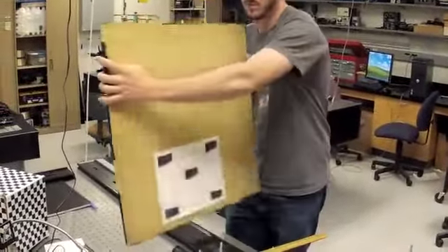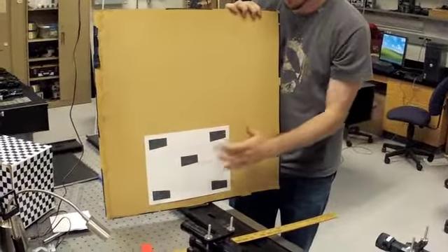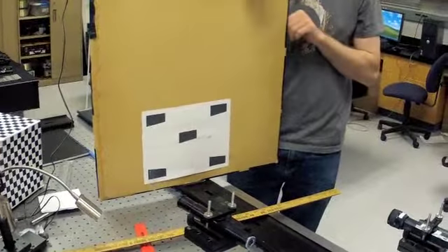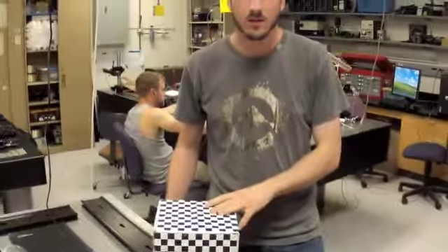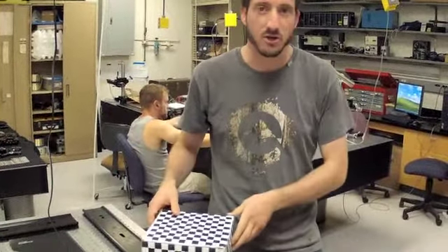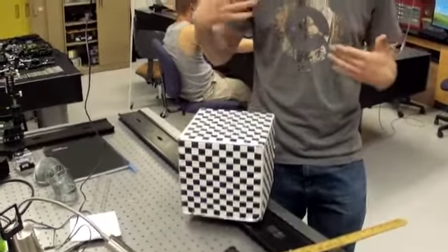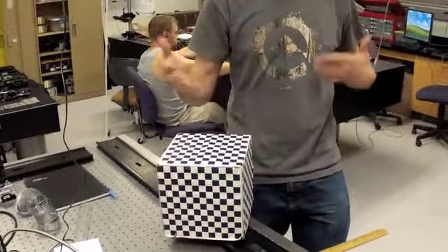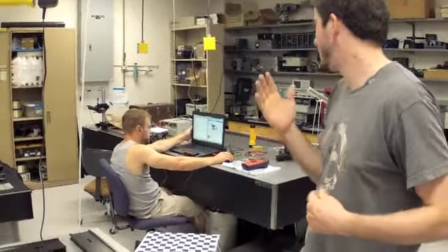We then flipped the checkerboard around and took images of the slanted edge profiles in order to get an MTF measurement of the camera system. Then for the final part of the lab, we used a cube to try to measure the angle of the two sides of the cube. We know that it should be 90, and so judging by this, we can tell how well we calibrated the camera.